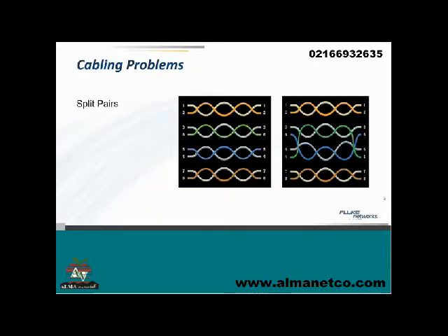Let's see, what else have I got? There's a few good comments that are coming up about the difference between more expensive and less expensive cable being the headroom, and that's correct. The headroom is the distance, the amount of space, between the amount of crosstalk that's allowed and the amount of crosstalk in the cable.